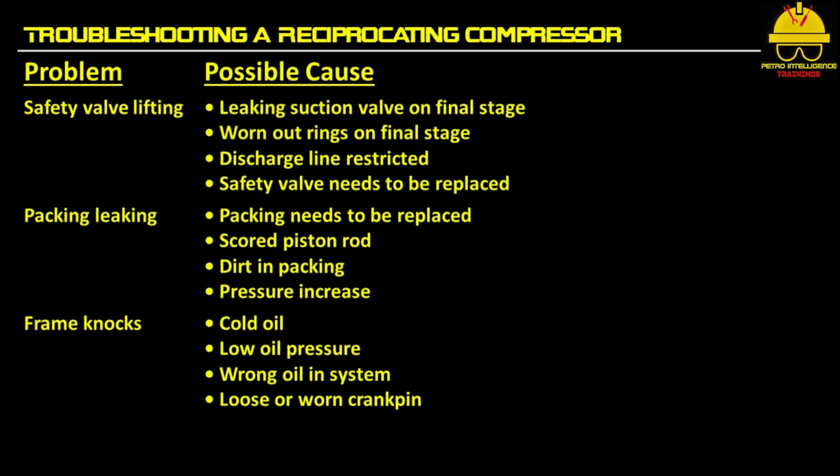If safety valves are lifting, there might be leaking suction valve on final stage, worn out rings on final stage, or discharge line restricted; the safety valve needs to be replaced.